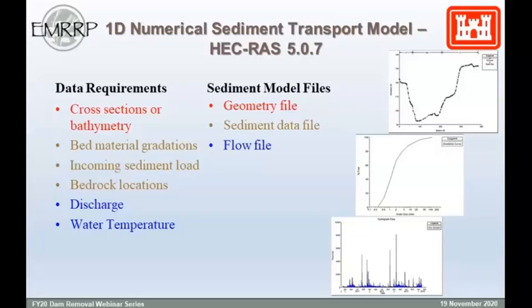This is important because you could set up the model to limit erosion. If you know there's bedrock at a certain elevation, you could specify that in the model so that it does not predict unrealistic erosion at locations where it's known that there's bedrock. That data goes into the sediment data file, which also has parameters. There are certain equations that you can pick to do your sediment analysis.